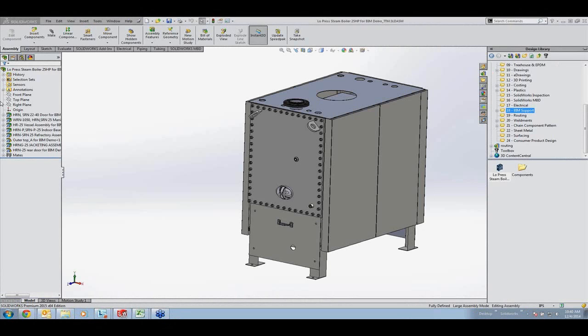I'm going to use the selection manager here to select my path. That's not correct. I meant to hit the little tangent propagation button there. I'm going to go ahead and accept that path. I can fill the path here, or I can select a number of entities to be patterned. Here I'm going to select my part.